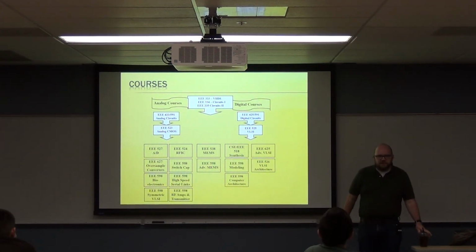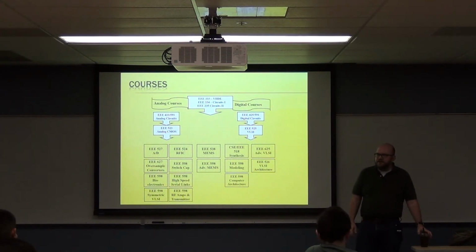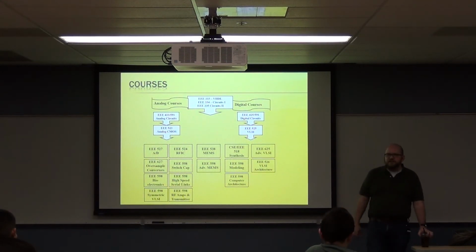Symmetric VLSI, so it turns out there's this awful thing. Some of you may have had this experience. You go and you try on clothes at the store. Same size, one fits, one doesn't. That's manufacturing variability. So you might think, well, that's because people make clothes. No, it's because it's built. There's just randomness in the universe, and entropy is awful. Turns out entropy is also in our devices. So when we build a transistor and you specify width, you actually get width plus some noise.